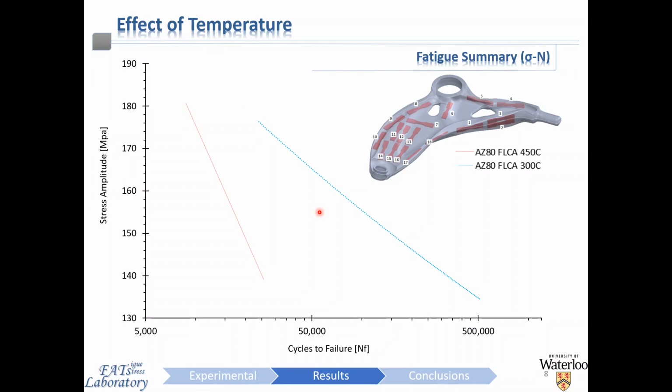Once again, it can be observed that under stress control fatigue testing now, so a different method of comparison, in the high cycle regime, for a given stress amplitude, the extruded material has a life which is superior to the as cast material by more than 10 times, as you can see here. Important note is that the materials being compared are from a full-scale forged component, so the effect of the processing temperature is really the most important in the last step of the thermal history prior to the in-service use. So, i.e., this isn't the extrusion temperature of the material prior to forging, but it is the die forging temperature and the subsequent cooling schedule after forging that governs the final microstructure.